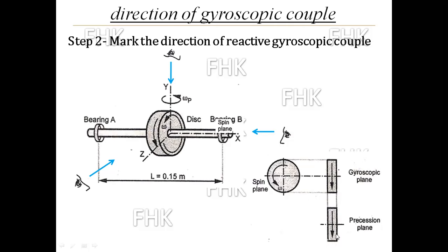So this will be the top view, and looking from right, in which you can see the actual rotation of the disc, this will become a right hand side view. A right hand side view, which you will draw left side of the front view, because in first angle projection method, a right hand side view you will draw left to the front view, and left hand side view you have to draw a right side of the front view.